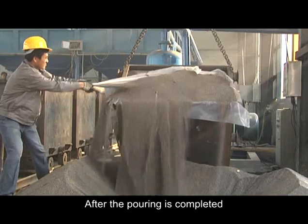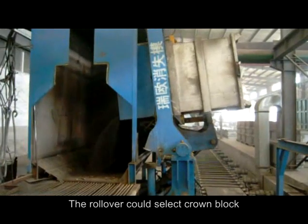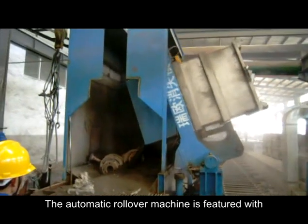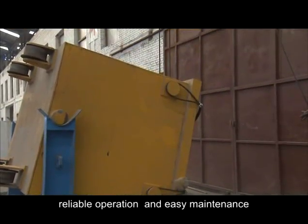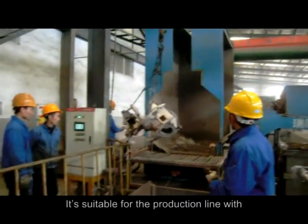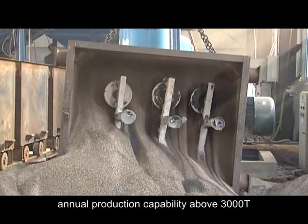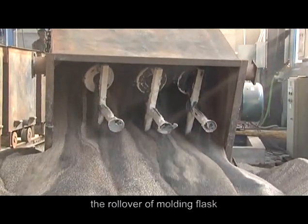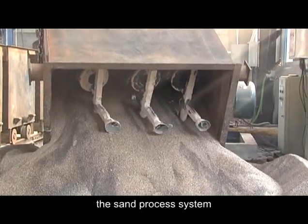After the pouring is completed, a rollover of the molding flask begins. The rollover could use crown block lifting rollover or an automatic rollover machine. The automatic rollover machine is featured with high efficiency, less dust, reliable operation, and easy maintenance. The workers do not have to work in the environment of high temperature and dust. It is suitable for production lines with annual production capability above 3,000 tons. The castings are collected after the rollover of the molding flask. The dry sand drops off at one time. The molding sands enter into the sand processing system.